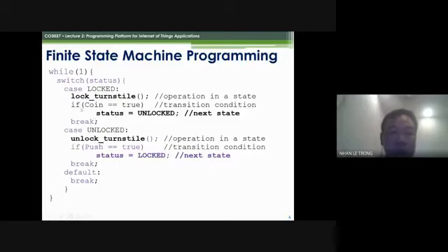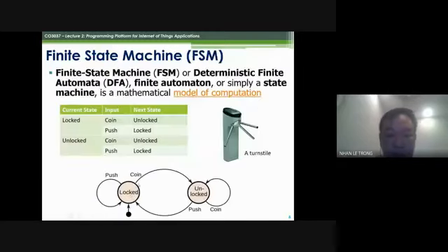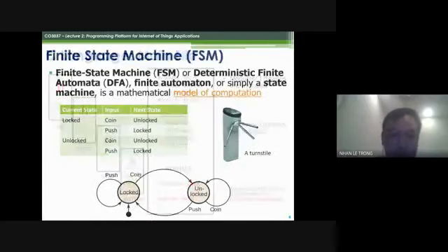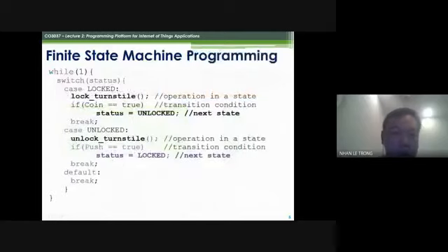Next, you need to implement the condition that changes the state from the lock to other steps. From the state machine before, we see that there is only one condition that needs to be implemented, which is changing from the lock to unlock. So you're going to have an if statement: you are in the lock, and if there is a coin, you change to the next step, and that's all.